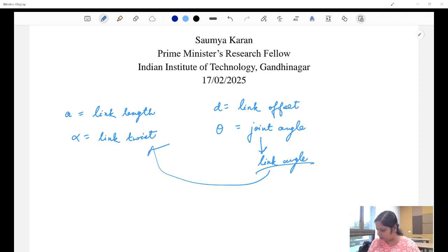I don't have it opened with me right now. But yeah, this is the joint angle, because this is essentially the angle between all the joints. So when we have a revolute joint and it can rotate by theta 1, we say theta 1 is my joint angle, and it can be used for calculating the homogeneous transformation matrices by calculating all the angles theta 1, theta 2, theta 3, as many as the number of revolute joints you have. All right, I hope I'm clear with this.